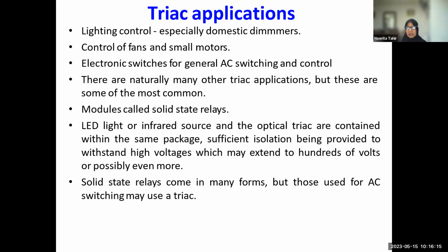Yeah, so here, what happened is actually the optical version of this semiconductor device is activated by an LED light source, turning the solid state relay on according to the input signal. So typically within this solid state relay, the LED light or infrared source and the optical triac are contained within the same package.